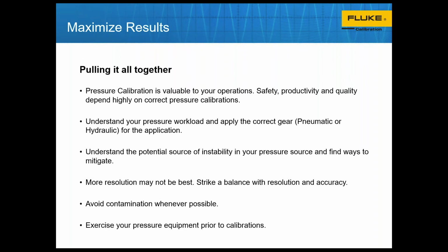Exercise your pressure equipment prior to calibrations. So if you have equipment that you know doesn't necessarily move a lot in pressures, take a few moments to run it up and down the span a couple of times and then do your as found.